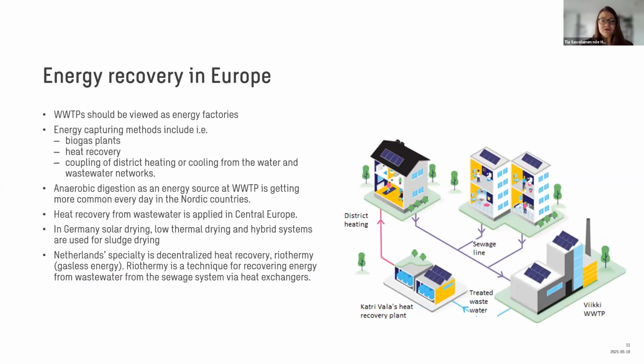And then about energy recovery. The wastewater treatment plants should be viewed as energy and resource factories, as in the Netherlands, as they have great potential. Energy capturing methods include, for example, biogas plants that produce biogas from wastewater treatment plant sludges with or without thermal hydrolysis or co-fermentation, and heat recovery from compressed air, from aeration, wastewater or effluent, and coupling of district heating or cooling from the water and wastewater networks.